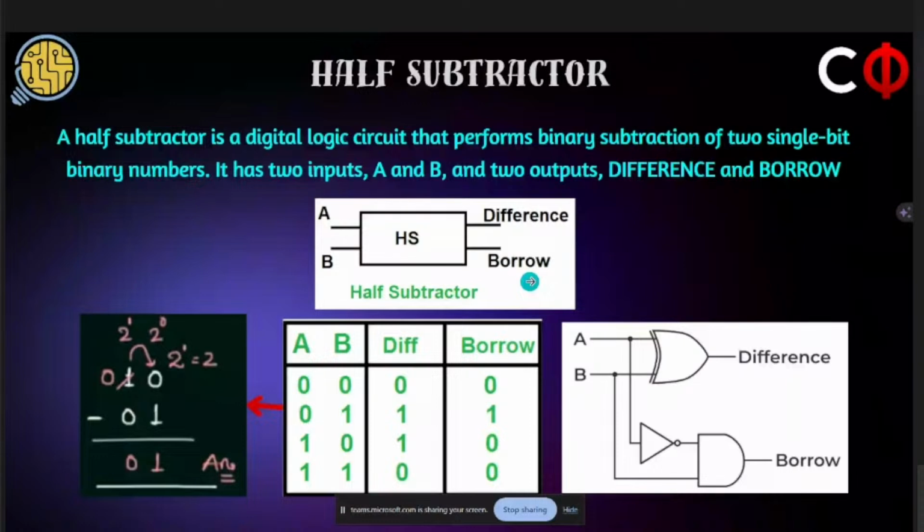Okay, so this is the truth table. When A and B are 0, difference is 0, borrow is 0. When A is 0, B is 1, difference is 1, borrow is 1. Why does this happen? You cannot subtract 1 from 0, right? So why do we get these outputs? I'll explain how using this example.